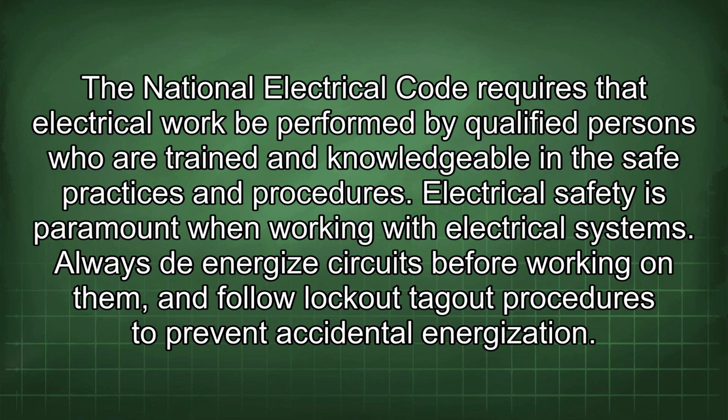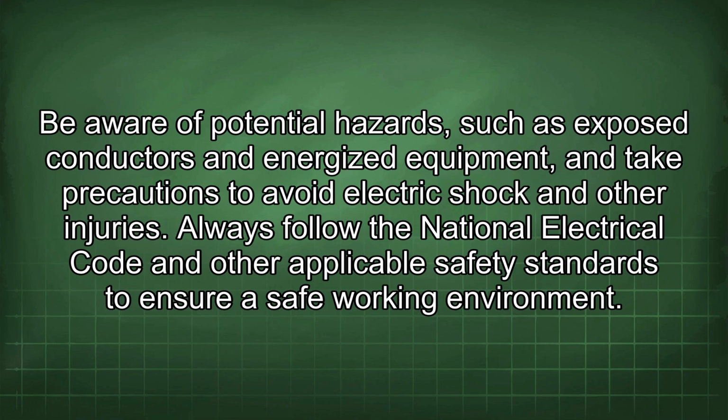Always de-energize circuits before working on them and follow lockout-tagout procedures to prevent accidental energization. Be aware of potential hazards such as exposed conductors and energized equipment, and take precautions to avoid electric shock and other injuries. Always follow the National Electrical Code and other applicable safety standards to ensure a safe working environment.